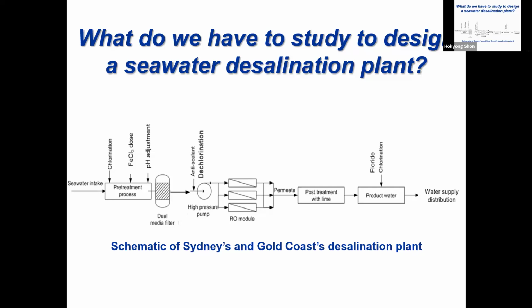So you can see the membrane crystal and then flux will decrease a lot. So how you can avoid this inorganic scaling problem? So anti-scalant can make the flow work even at high recovery or high concentration of salt.